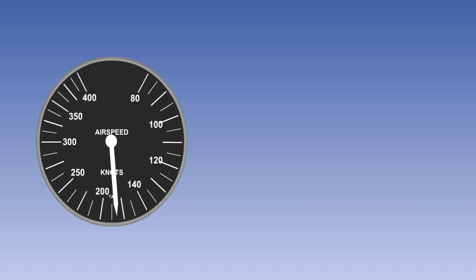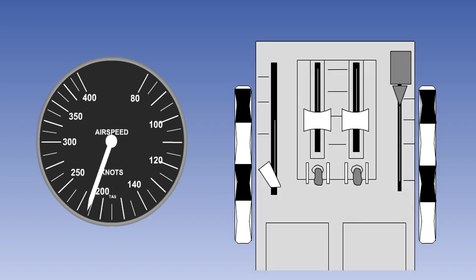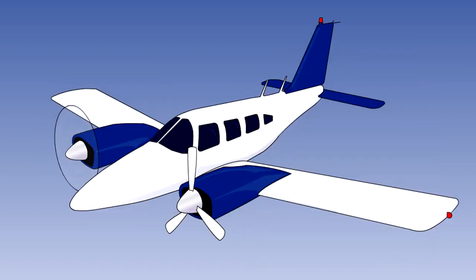The aircraft will need to be trimmed in pitch as a result of changes of speed, changes of power, or varying centre of gravity positions. Trimming in yaw will be needed on a multi-engine aircraft if there is asymmetric power, or on a single-engine aircraft as a result of changes in propeller torque. Trimming in roll is less likely to be needed, but could be required if there is asymmetric power, or if there is a lateral displacement of the centre of gravity.